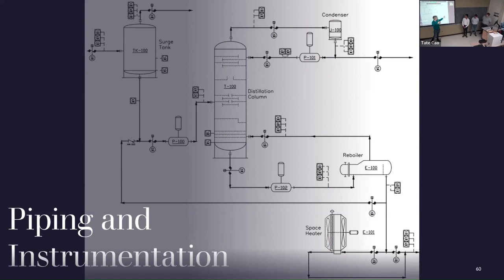And then the water that is not evaporated in the reboiler is sent through here, tested for purity. If it doesn't reach the purity that we want, then it's sent back around to be reprocessed. When it is at the purity that we want, we can use the heat that's in that to heat the enclosure that this whole system is going to be in.